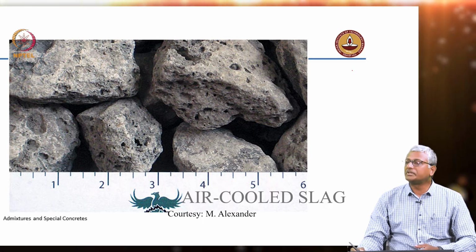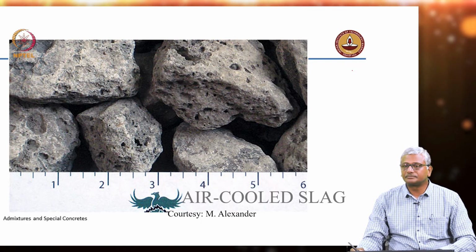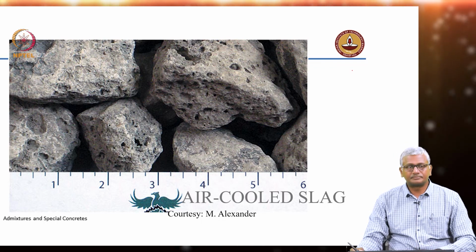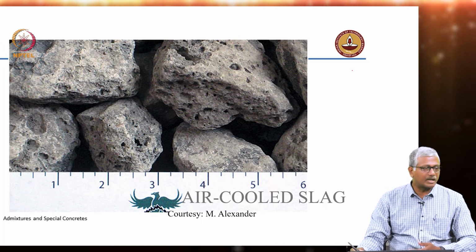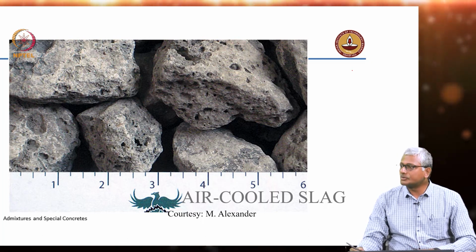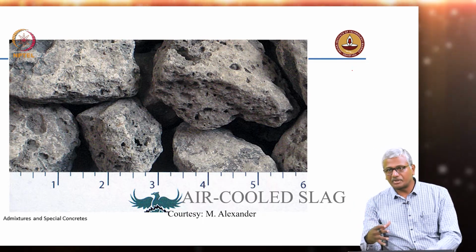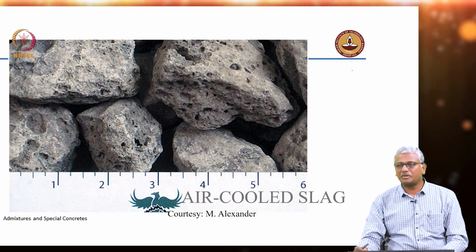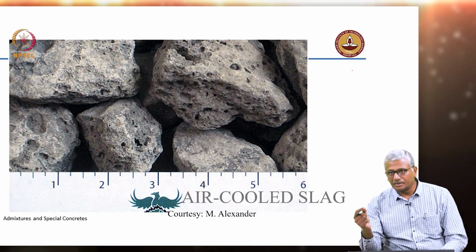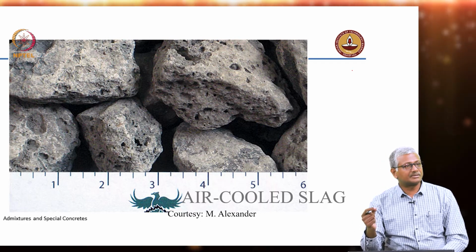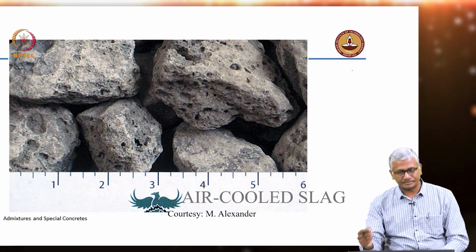So, what will be the relative hardness of slag as compared to cement clinker or as compared to limestone? Slag will be less or more hard? More hard. It has got iron in it, it is going to be more hard. So, crushing slag into aggregate sizes from the large bulk may be quite energy intensive. Similarly, crushing slag into very small sizes to become a cementitious material is also fairly energy intensive.